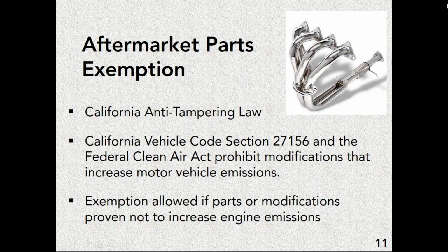I wanted to get a little more information from the person before I asked you, but they have a pretty specific instance. They're trying to install a DPF on an off-road loader that has an opacity reading currently of 27%. And this is for port as well, so cargo handling. The standard is 40% or lower on the engines. DCL refuses to sell the filter because they want a reading of 20% to install it.